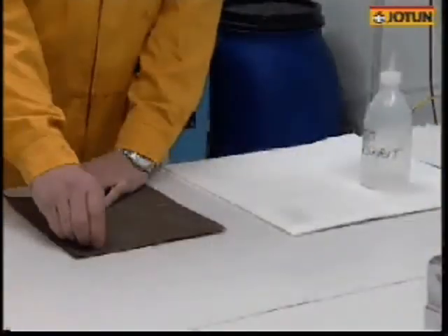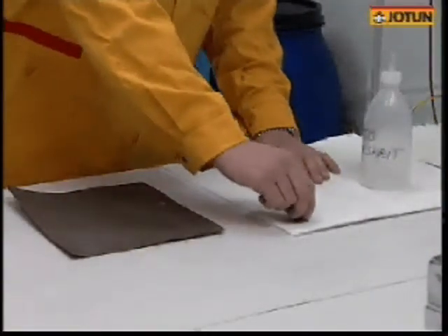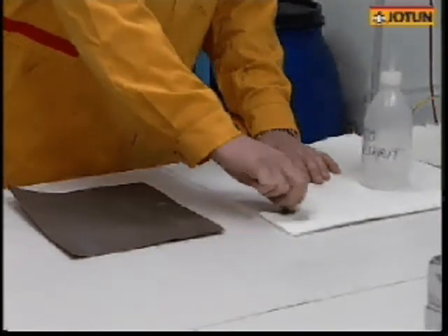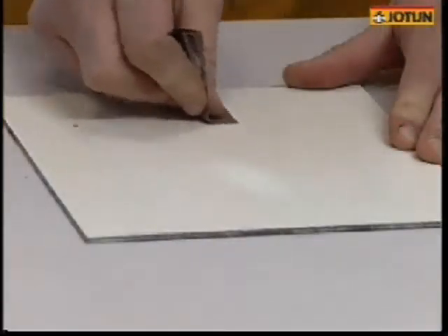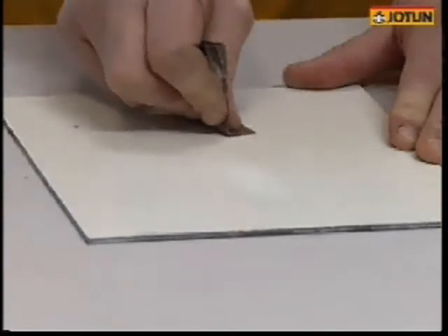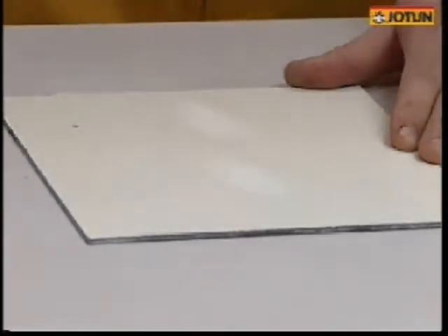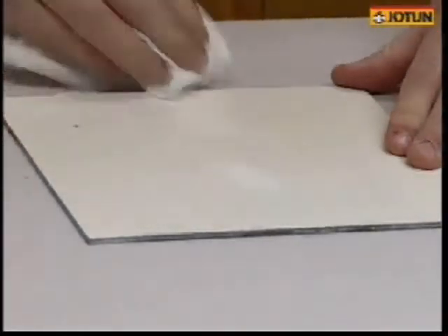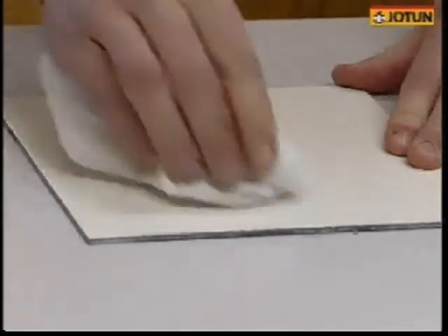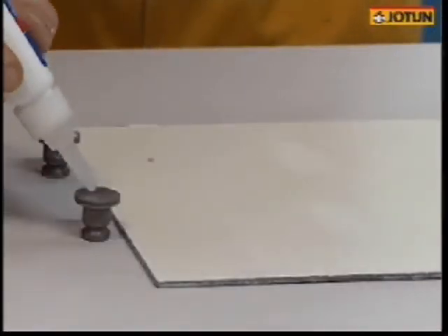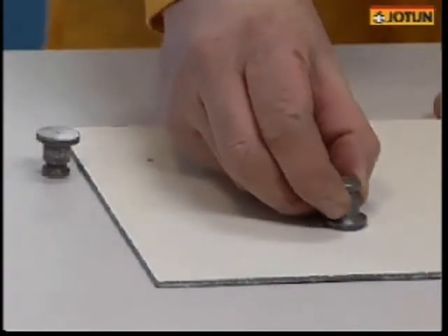Start the testing by grinding and cleaning the dolly thoroughly. It's advisable to rub the paint to remove inactive layers and to improve the adhesion to the dolly. Remove the dust before gluing the dolly to the painted surface. Make sure you use the correct type of glue and let it cure for as long as required.